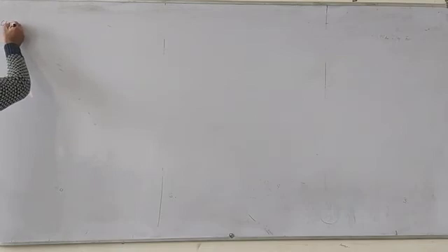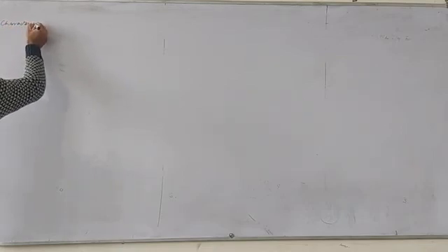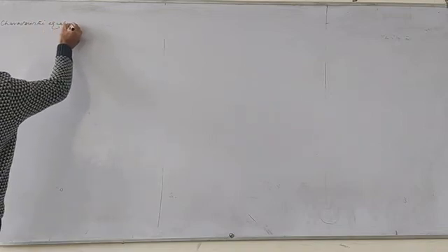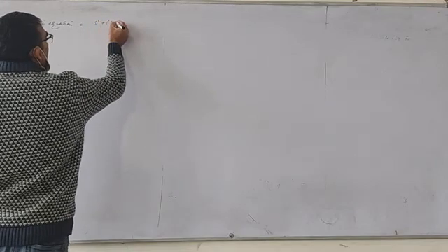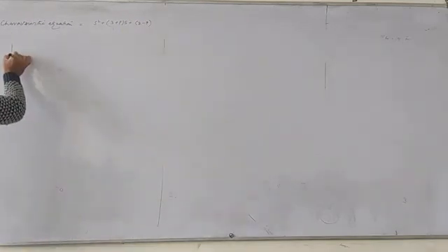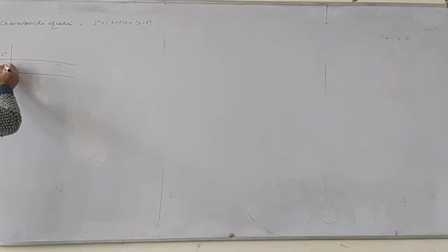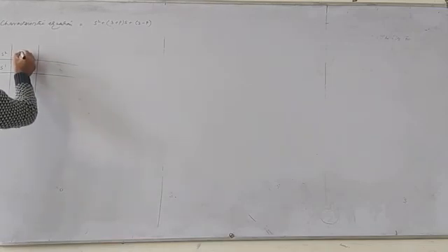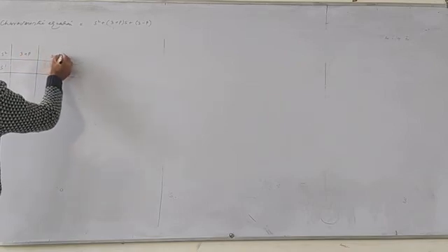First, you form the Routh array. The characteristic equation of GP of S will be, what is that? That is given: S square plus (3 plus P) into S plus (2 minus P). Okay, you form the Routh array. I'm not writing it, but it's very clear. S square is called 1. The first term is what? 3 plus P, and then we have 2 minus P.